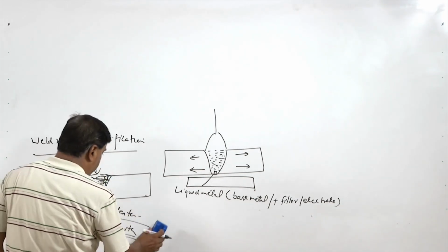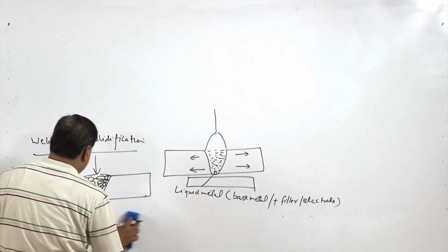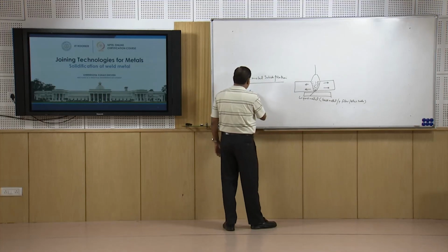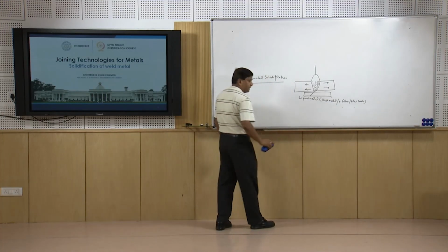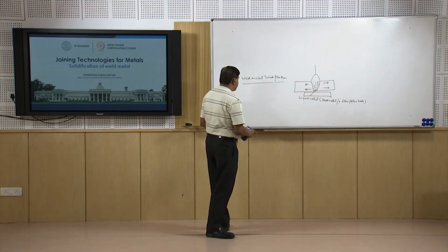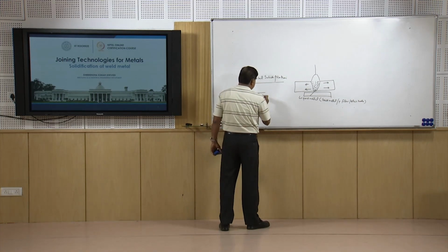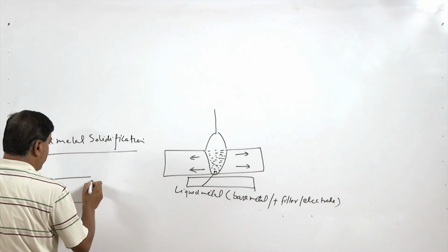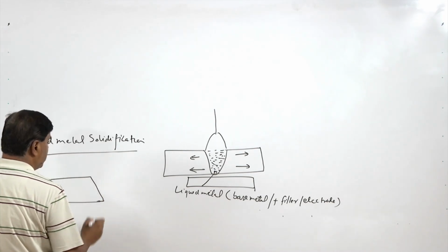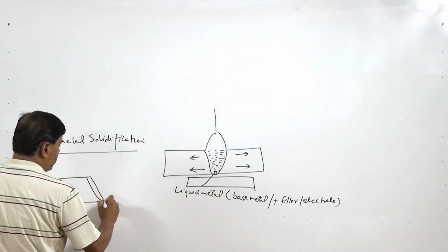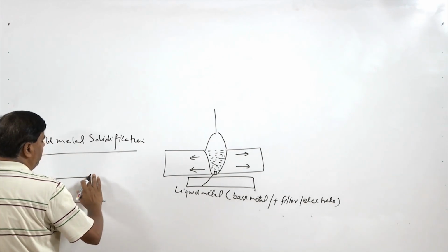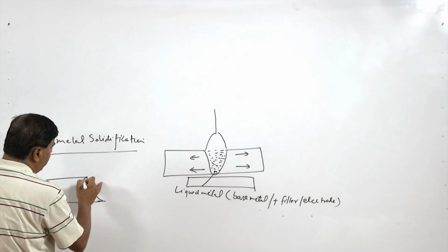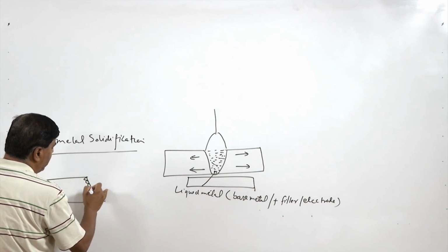This is what happens typically when the nucleation and growth mechanisms are involved, and when completely different base metal and filler metal compositions exist. And when the two are the same, then what we will see, like say this side we have the fusion boundary. So, when we fuse the things it will have typically the curved surface, and at the fusion surface we will have partially melted grains